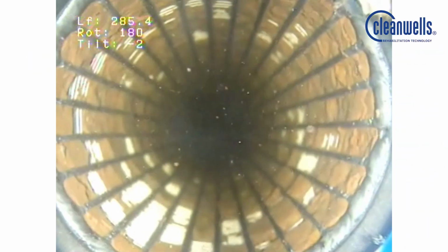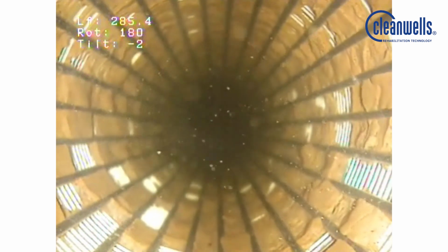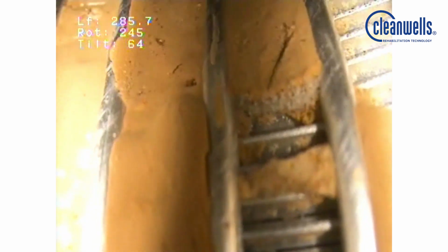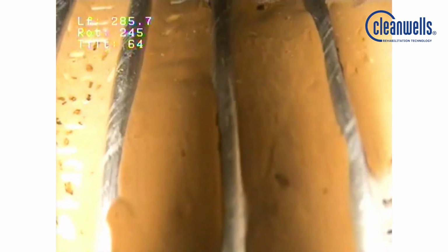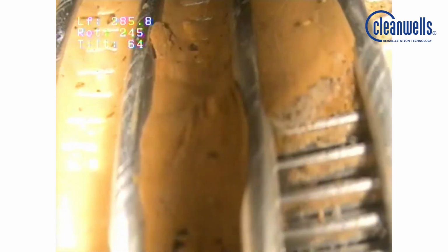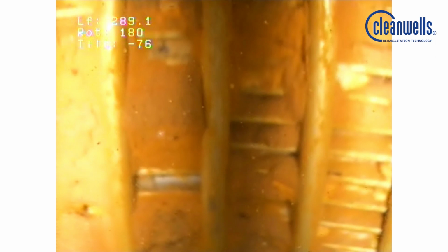The aim of every well rehabilitation is to restore the original functionality by removing mineral and organic deposits from the inner surface of the pipes, screen slots, external surface of the screen, as well as from the gravel pack and the adjacent geological formation. W130, the technical bulletin of the German Gas and Water Association, defines a state-of-the-art rehabilitation, including